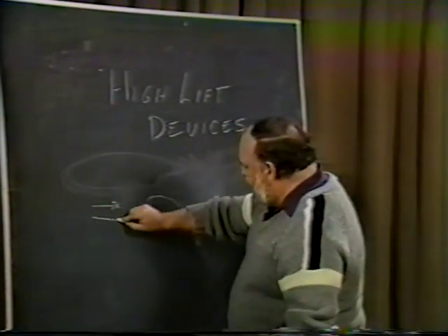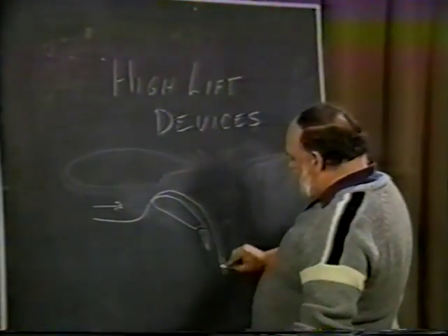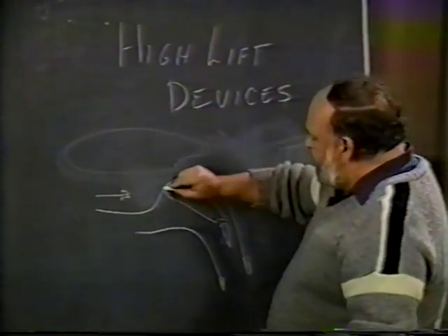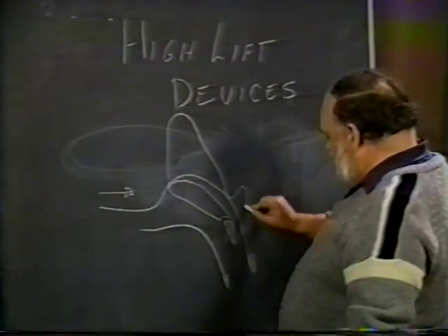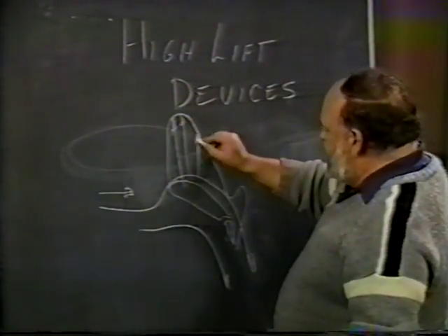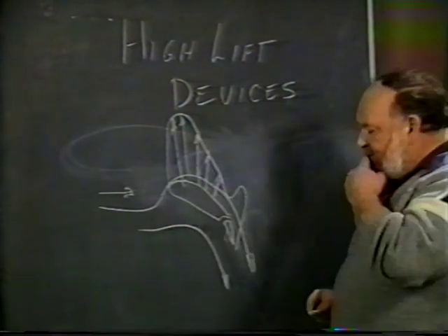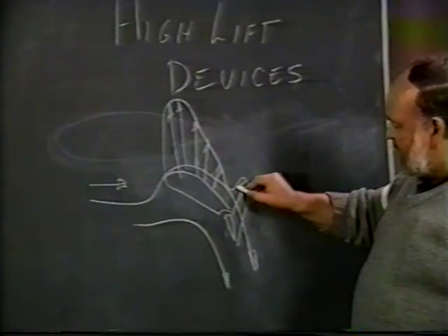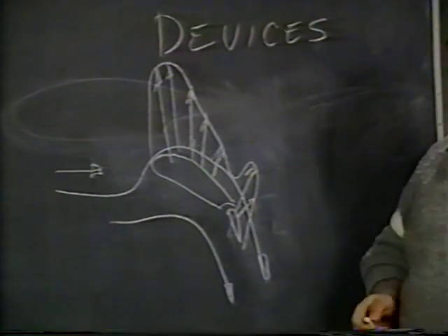What's going to happen is the air is going to come up over the wing, speed up and come down the trailing edge here. The air on the bottom will, of course, be deflected down too. What this will do is produce a lift pattern that is something like this. These could be visualized as vectors demonstrating how much lift, or force, is being exerted on the airfoil. A lot of people believe that when you deflect the flap down, it produces a low pressure above the surface of the wing of the flap itself, and that produces lift. Yes, it does.